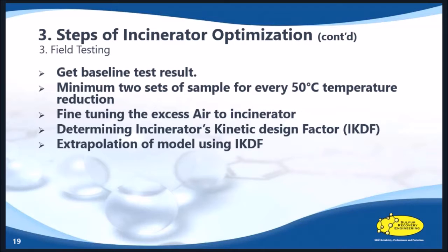In order to produce an accurate incinerator TRS destruction efficiency model, as well as a plume dispersion model, an accurate heat and material balance must be created. In order to accomplish this, SRU feed stream samples are needed, or in short, we take samples in and out of the sulfur recovery unit to assess the overall recovery efficiency of the unit.